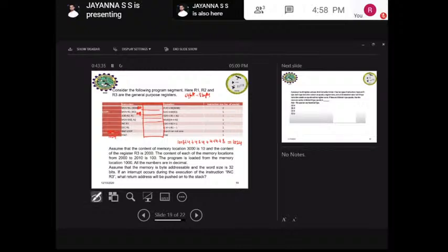Whenever an instruction is executed, as we know, when the processor is executing the current instruction, the PC is always loaded with the address of the next instruction. Then whenever an interrupt occurs, what will happen? It stops the currently executing instruction and pushes the address of the next instruction onto the stack memory. That is 1024. The address 1024 is pushed into the stack memory. Therefore, the return address pushed onto the stack is 1024.